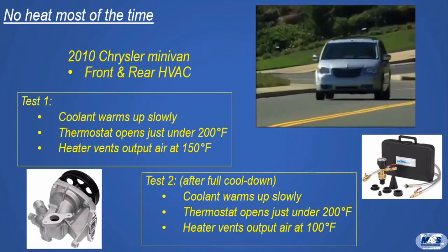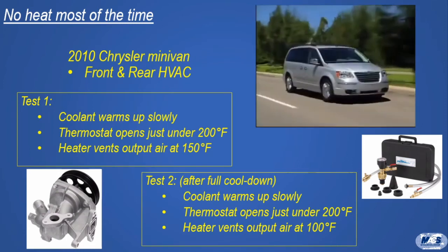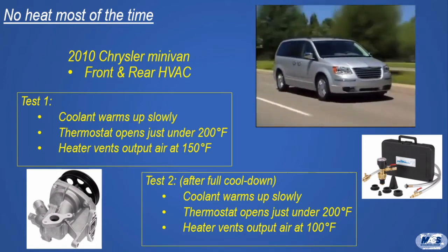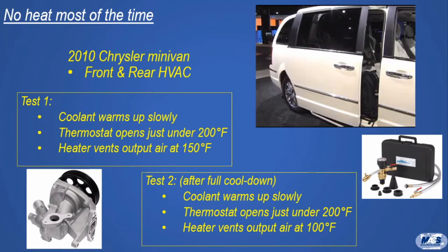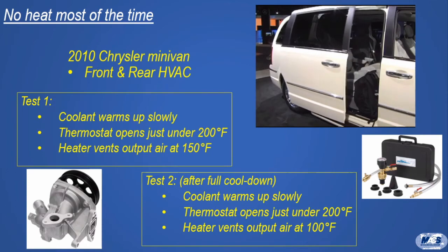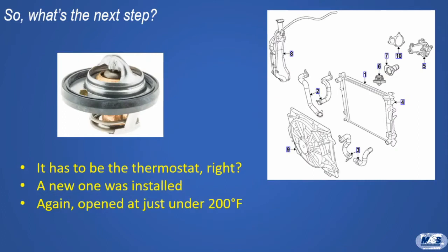For some reason, the technician not only checked the water pump, but he convinced himself that it needed replacement. After reassembly, he used an airlift vacuum tool to top up the system, but the problem remained. So, what's the next step? Well, in this general sequence, it has to be the thermostat, of course. So, a new thermostat was installed.